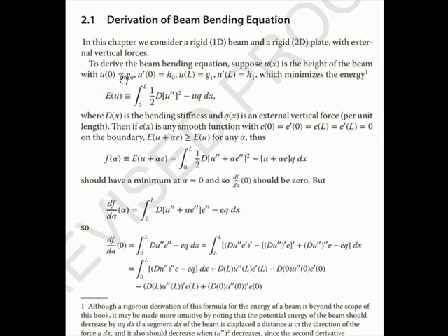And we're going to have boundary conditions on each side. We have that U and U prime are given at x equals 0 and x equals L, the two ends of the beam. The height and the slope of the beam are given. So it's called clamped. These are clamped conditions. Basically think of the beam as being stuck in the wall on both ends, and not only the height but the slope is fixed by how it's stuck in the wall.